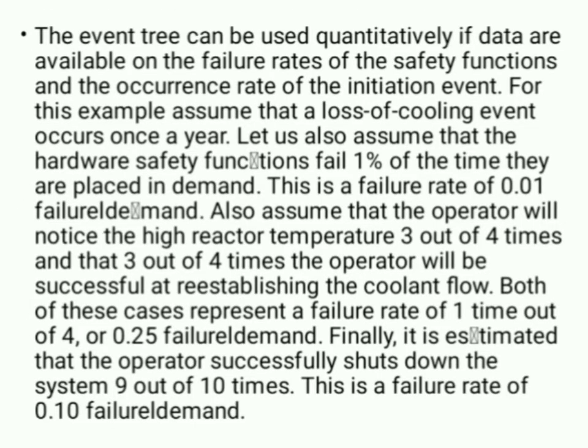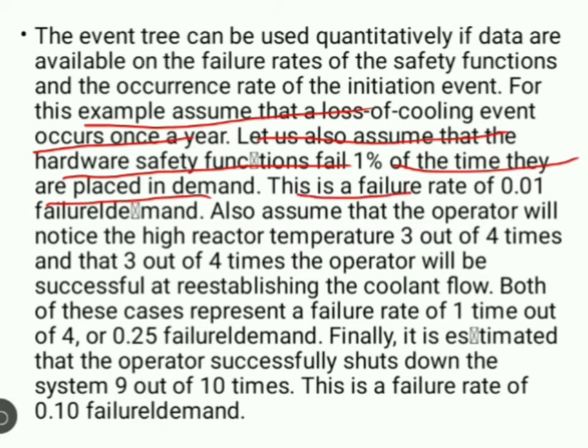Now we can see here from the diagram. For this example, assume that loss of cooling occurs once a year. Let us assume that the hardware safety function fails 1% of the time it is placed in demand. So this failure rate is 0.01 failure per demand.